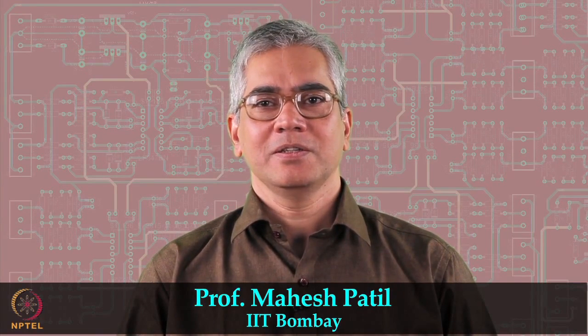In summary, we have completed gain calculation for the common emitter amplifier. Also, for a given input signal, we worked out the complete solution, that is DC plus AC, and compared it with simulation results. We have taken a qualitative look at the variation of the amplifier gain with frequency and pointed out the factors responsible for this behavior.